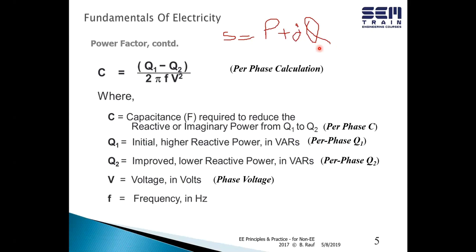So when your power factor is poor, it's because of too much inductive reactance, which drives up the Q, the reactive power Q, the VARs. And when Q goes up, the S goes up. The real P does not change. The real power, the torque required by the load, whether it's a pump requiring that torque, or a conveyor belt you're moving sand on, or whatever, that is not changing. That stays constant. That's one way to look at it. So when you add a lot of inductance in the system, Q goes up and S goes up.